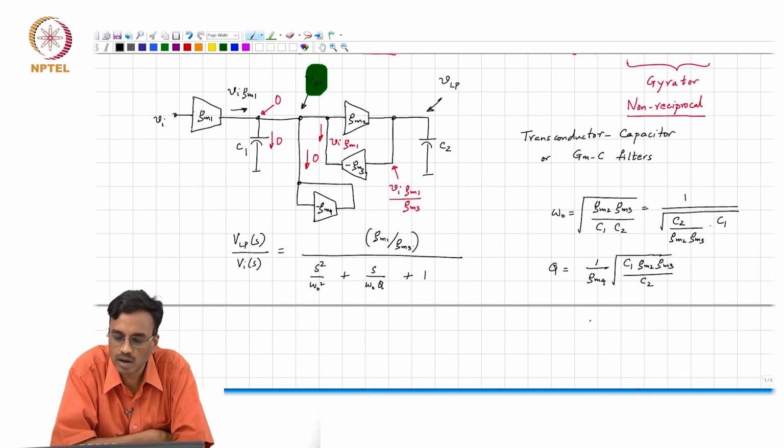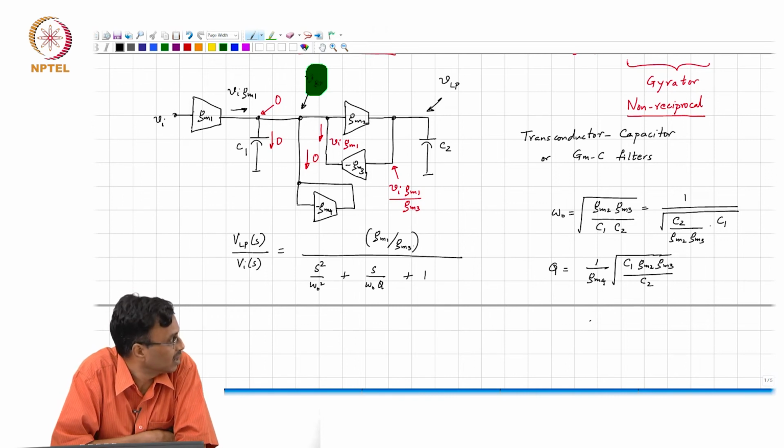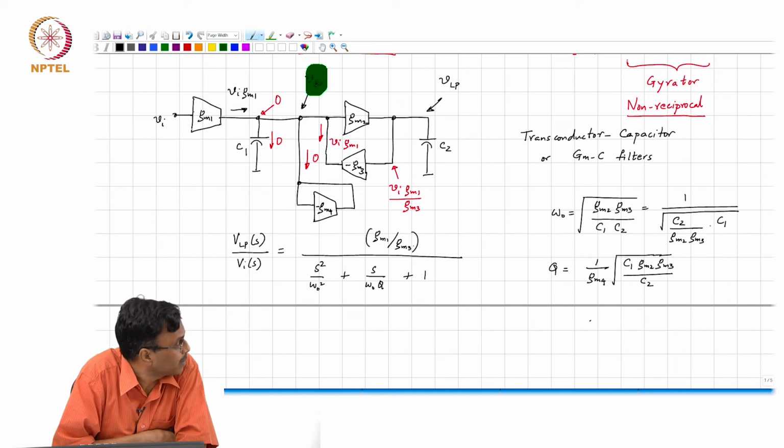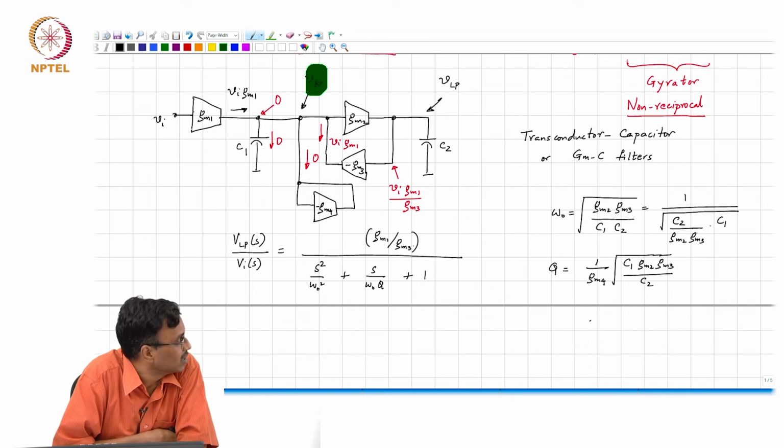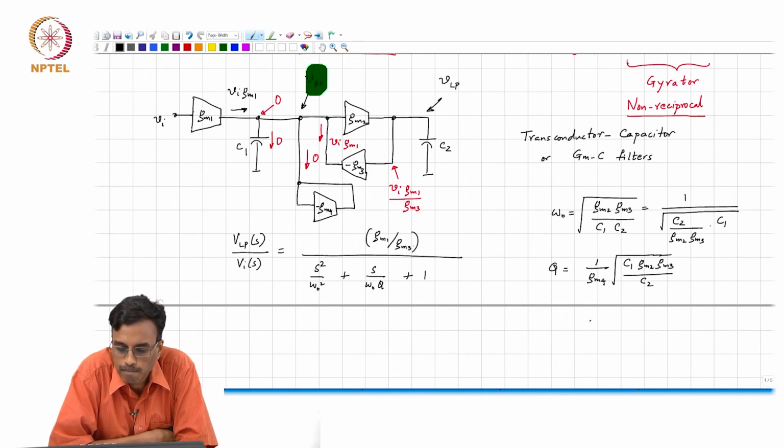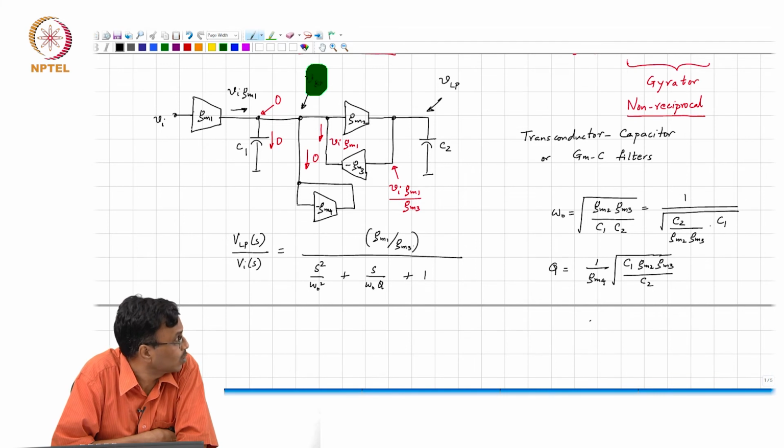Now here, what do you think our situation is? What is the output impedance? Is it 0 or non-zero? That's all I'm looking for. It is non-zero, right? If you actually look at it carefully, it turns out to be a C in parallel with an LR in series, but it's not 0. What comment can we make about the input impedance, however?